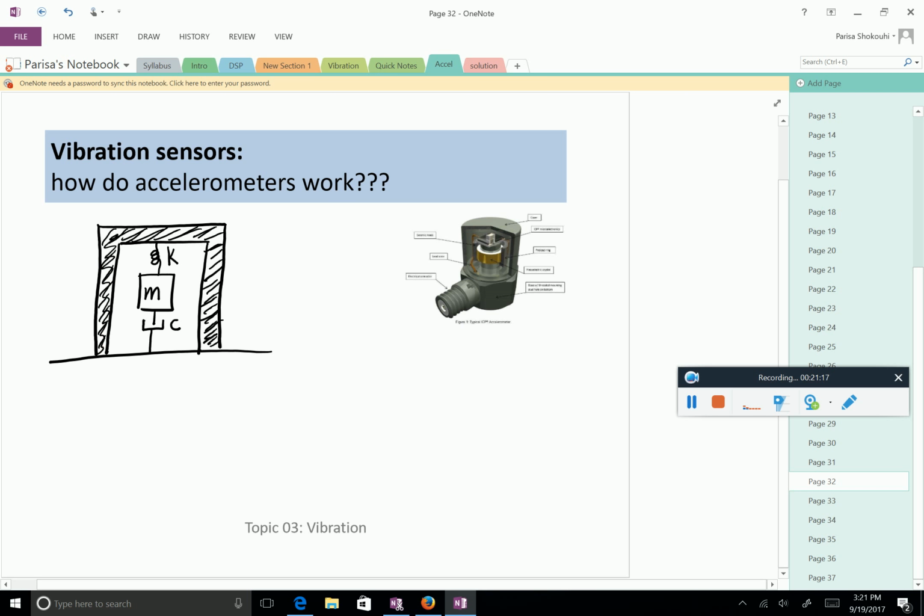And you saw that today Jiyoung was gluing or using a wax to attach the accelerometer to the surface of, let's say, the aluminum sample or the Mylar sample. If you use it to measure ground vibration, you kind of place it, you cement it to the ground. It will be much larger. Those triaxial, you probably use geophone, not accelerometer, but it is similar. So this is the ground. And I use G for anything related to the ground.